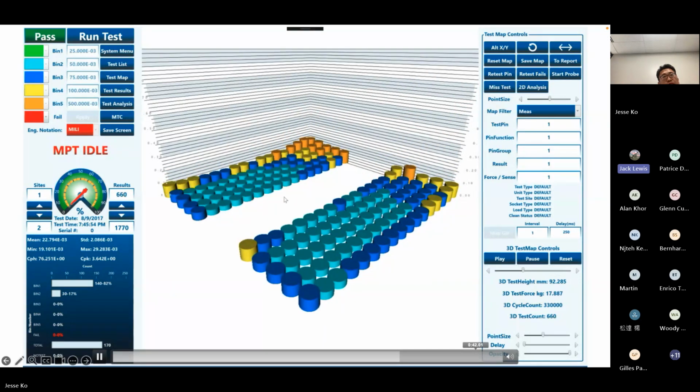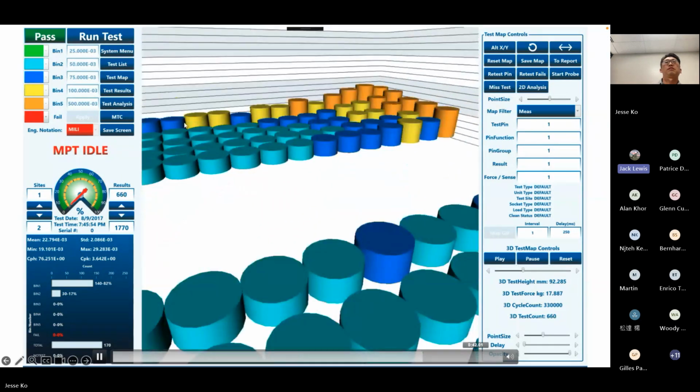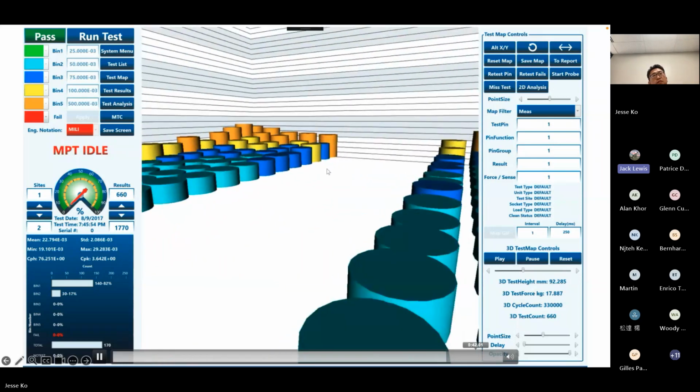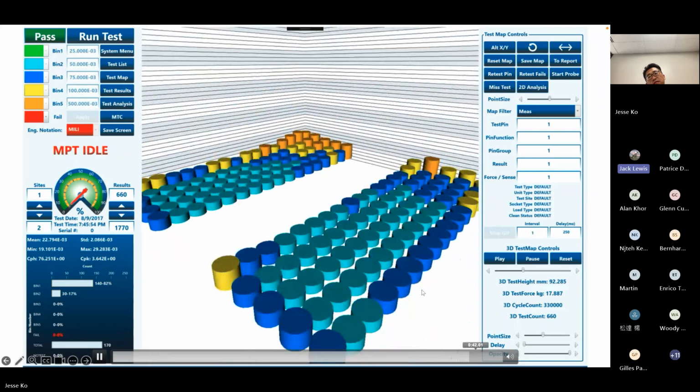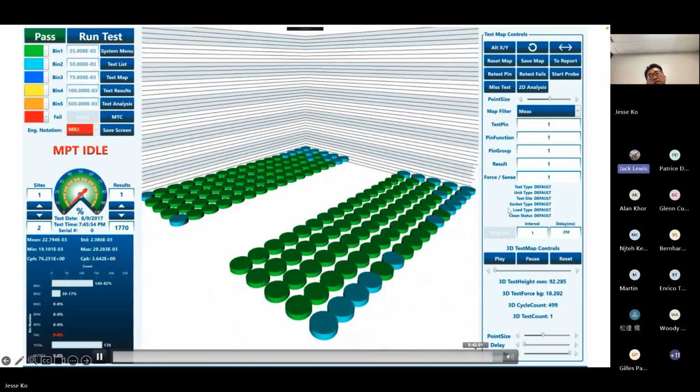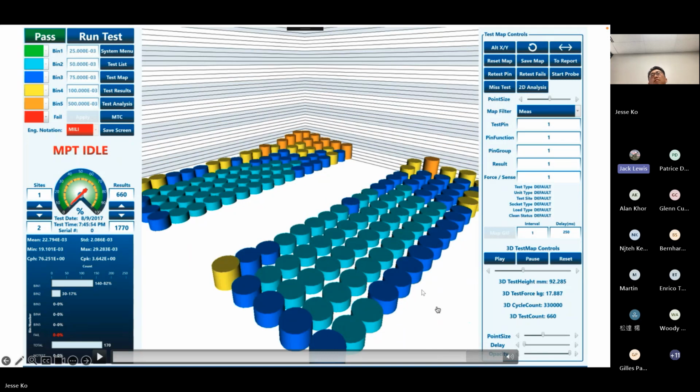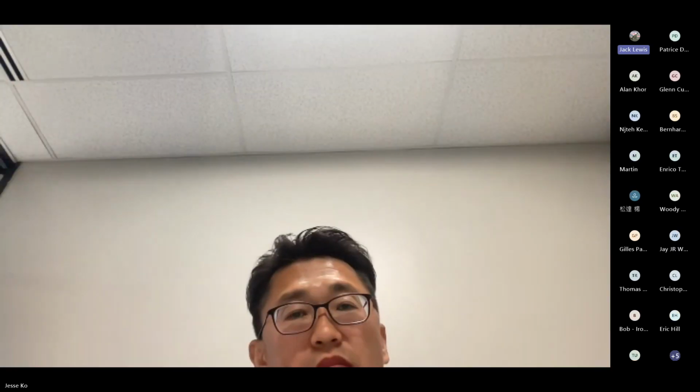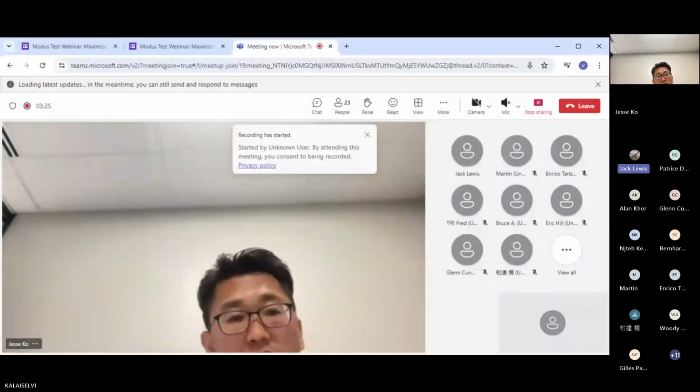For example, a picture's worth 1,000 words, and a video even more, because in a quick 5 or 10 seconds, you can tell that we have a boundary issue within this socket over the life cycle. And when we go investigate this particular one, it's the same contact point throughout the array, but the edges wore differently. In this particular case, there was not sufficient support structure at the boundary of the elastomer, so it failed there because it was essentially leaning.